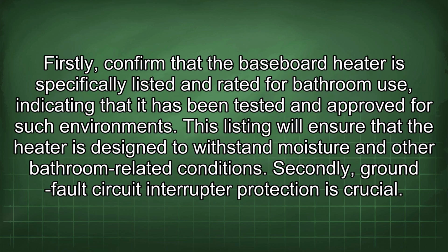Firstly, confirm that the baseboard heater is specifically listed and rated for bathroom use, indicating that it has been tested and approved for such environment. This listing will ensure that the heater is designed to withstand moisture and other bathroom-related conditions.